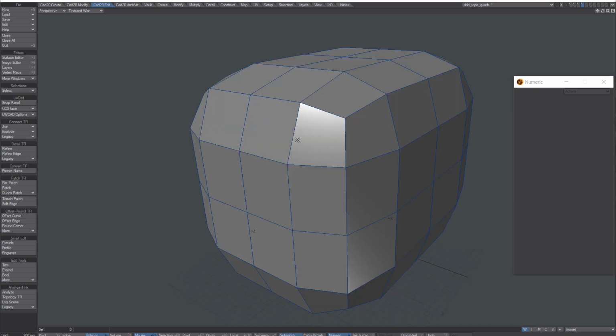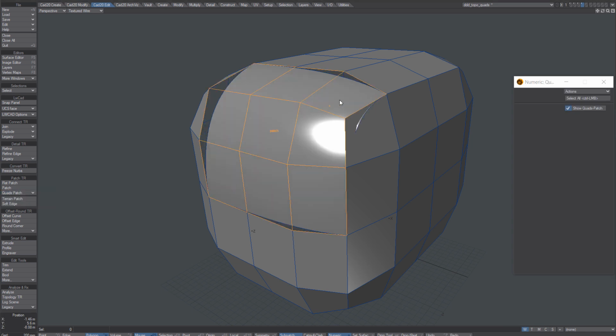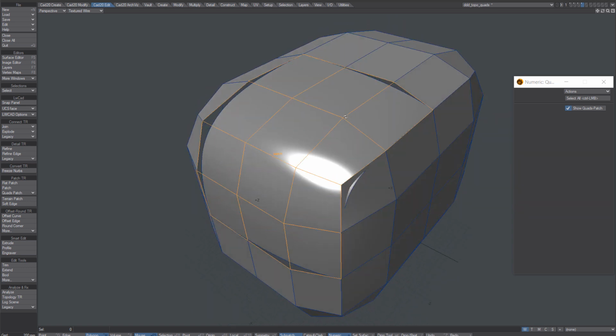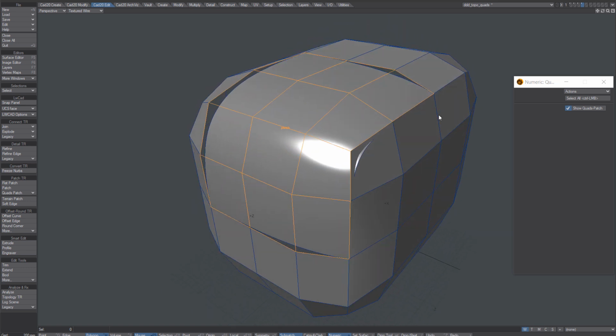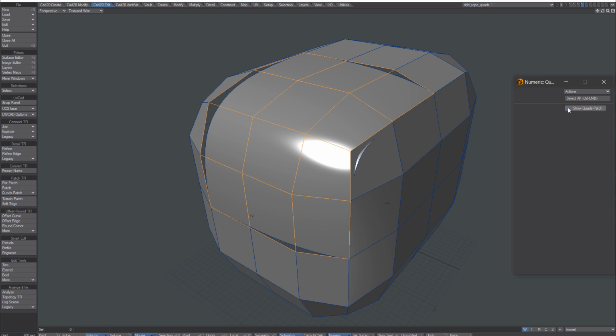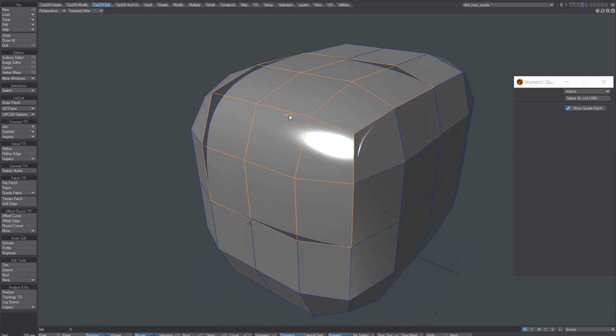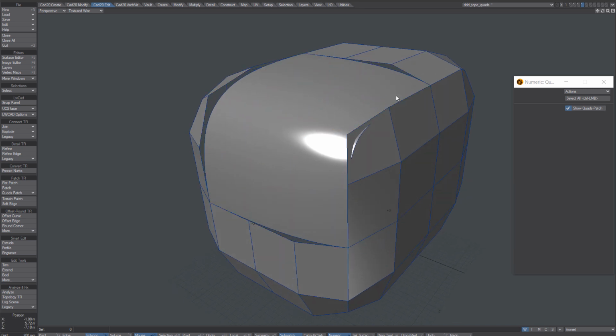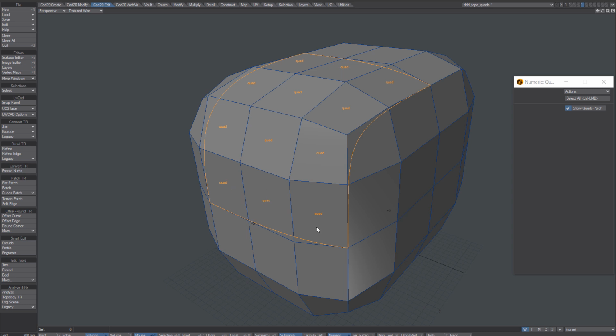And finally, some small additions in quads to patches and patches to quads modeling. Quads patch is the tool that can convert quads into a single patch by selecting the grid of quad polygons. And now we have an additional show quads patch option, which will show you directly in the viewport the final geometry type. So now it is a patch. If you use this tool on existing NURBS patches, then it will show you new quads. So this is much more convenient.